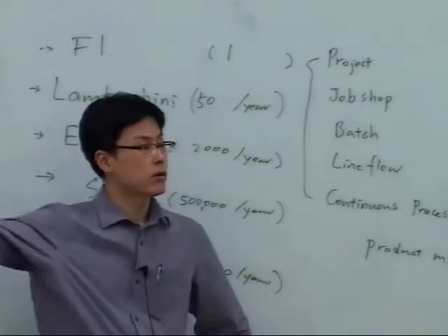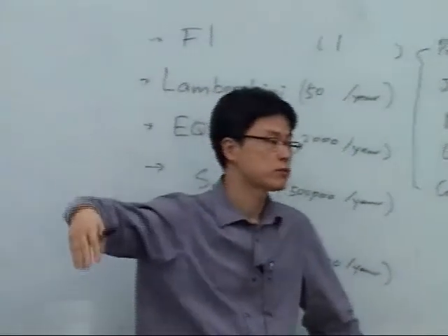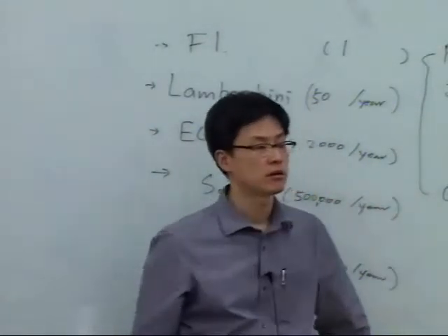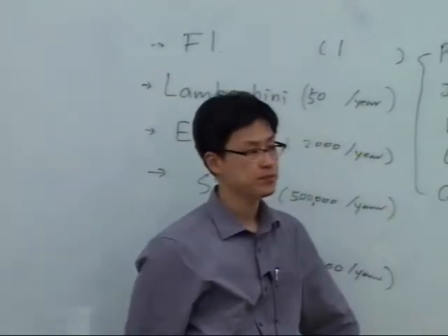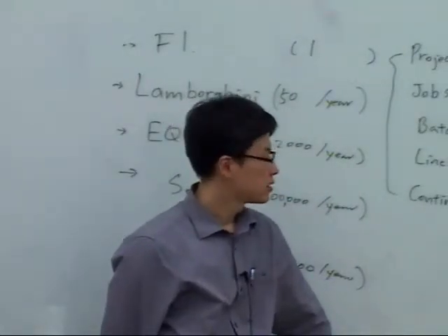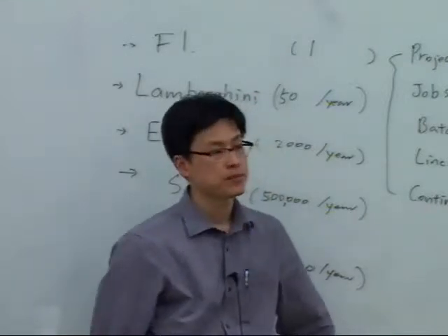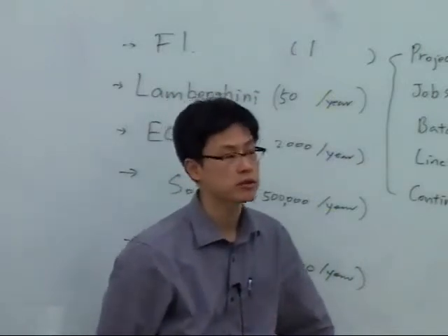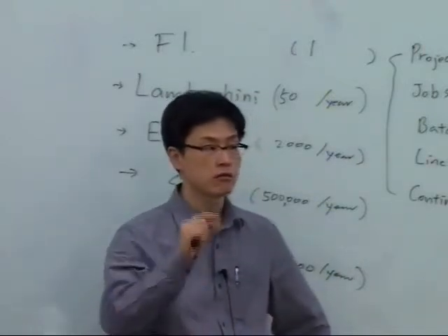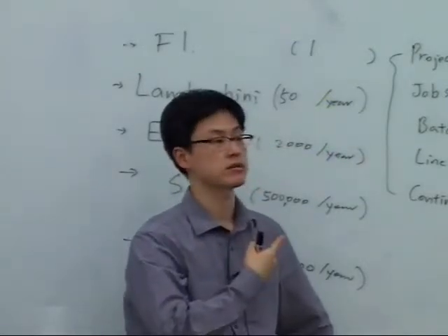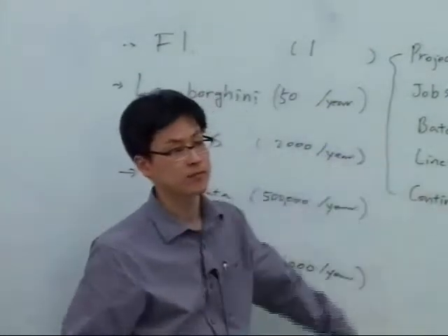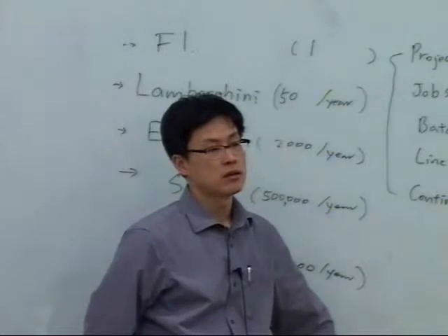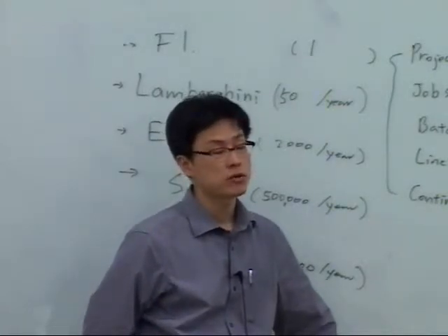The ship is produced from stockyard, surface preparation, primer, cutting, marking, until it is outfitted and sea trialed. We know the required steps. The next thing is, based on each intermediate product's characteristics, we have to choose the right kind of processes. Once you choose the right processes, the required information will be derived.